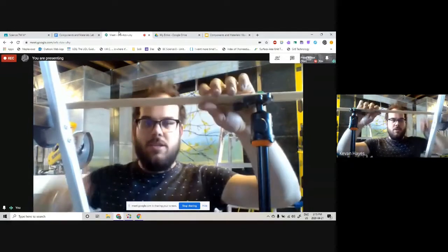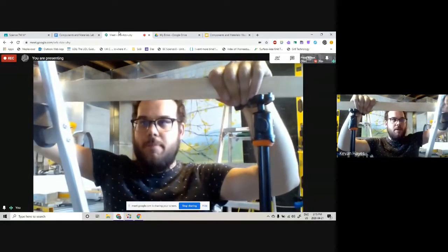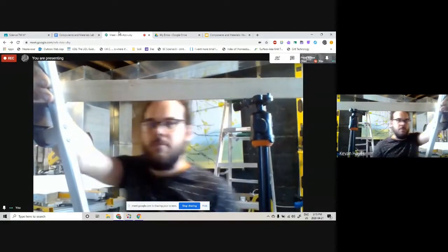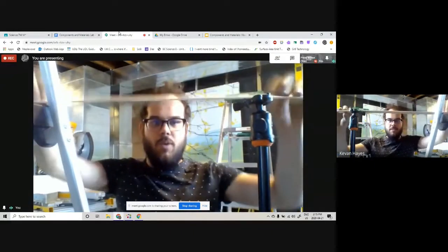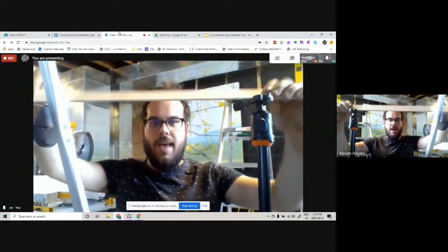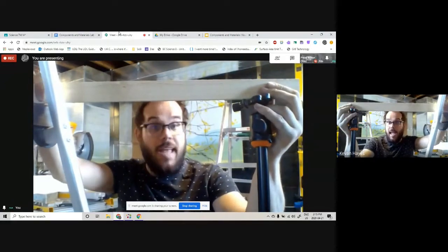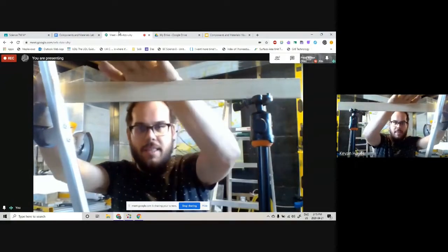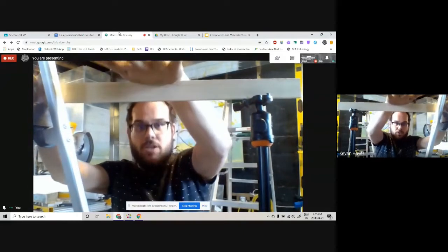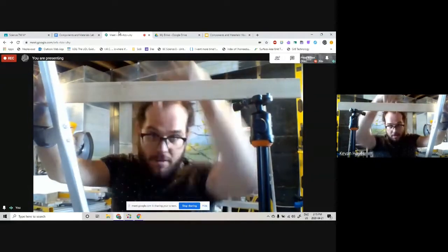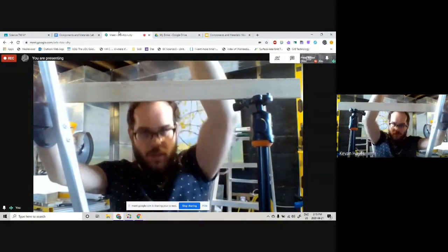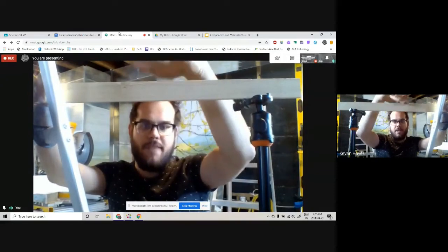So the other thing you could do is take this and flip it up on edge. Now, when it's on edge, it wants to flop over. It's not very sturdy that way. But if you can find a way to support both ends so that it can't flop over, then suddenly this is a much stronger beam if it's experiencing force directly down, like gravity or something like that.